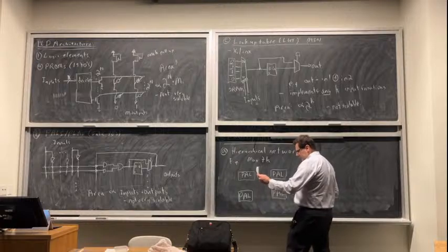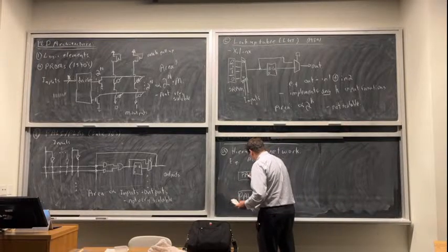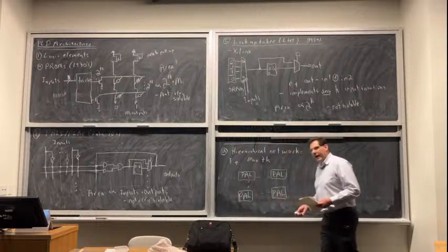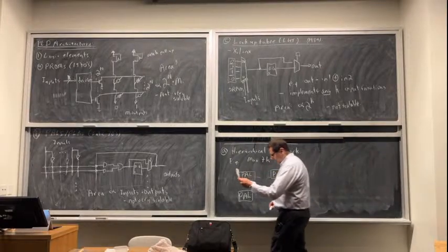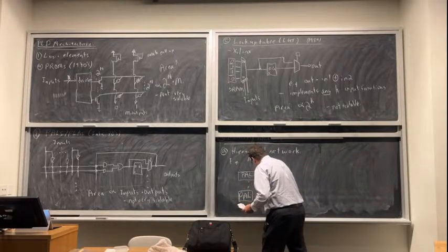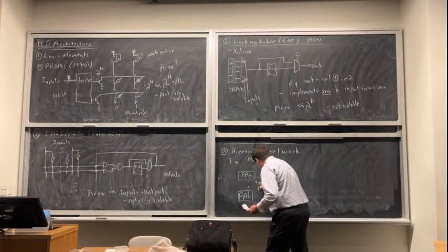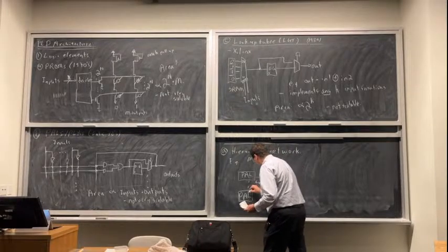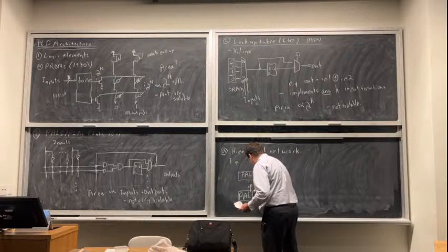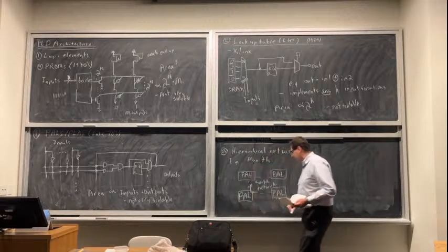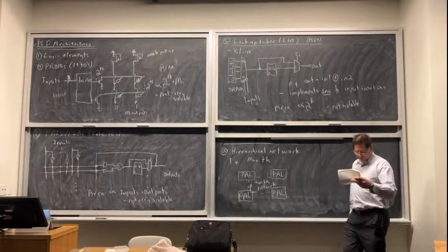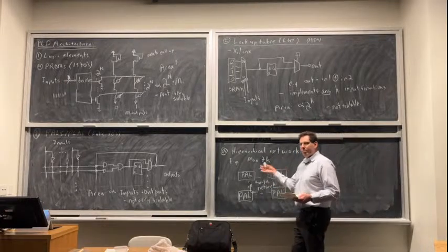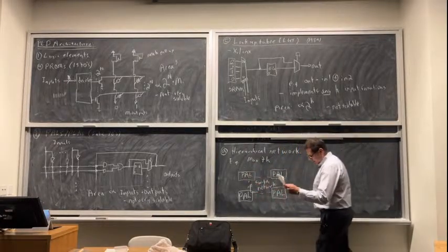So we'll just make a bunch of these on one chip. And then in between, we're going to put a switch network to allow their inputs and outputs to connect to each other. So it kind of behaves like a single bigger programmable logic device. Okay, so we've got some outputs that go into the switch networks. We've got some inputs that come from the switch network. All these things can now talk to each other through this. And so this is how all programmable logic is designed now.